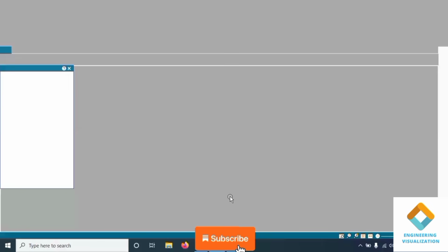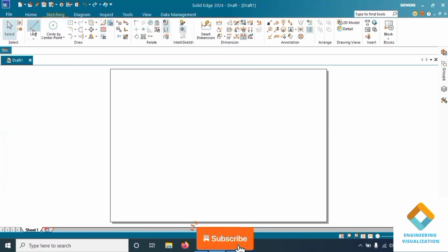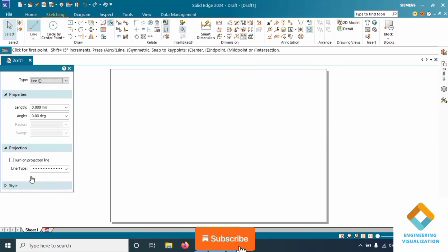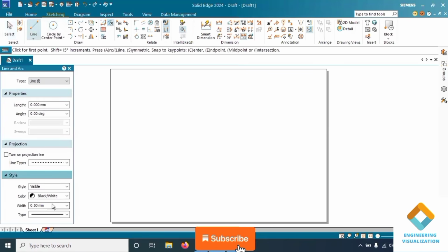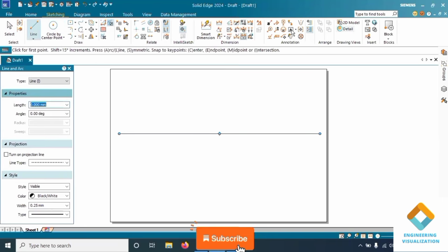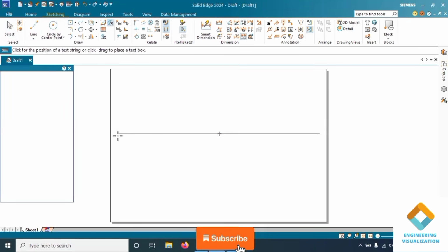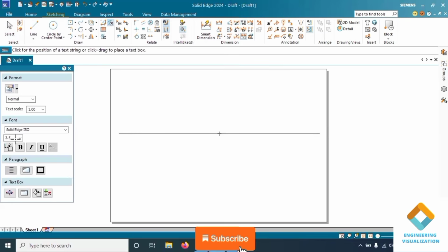So in this problem we have to use the dimensions of the ellipse, that is major and minor axis. The circle dimensions they have not given, and it appears in the front view. That is, we need to use the major axis of the ellipse, 60 mm, in order to construct the circle. This is one of the special types of problem. In this problem they have not given any kind of inclination. We have to use the data which is given in the problem to solve it.